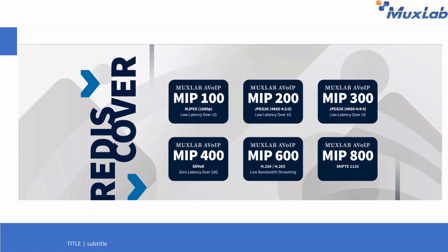However, if you need a better solution because you have a 4K 420 signal, you could use a JPEG system that will handle that with the MIP 200, or you can actually move over to the MIP 300 for a JPEG system that will allow you to use 4K 60 444 signals on your system.